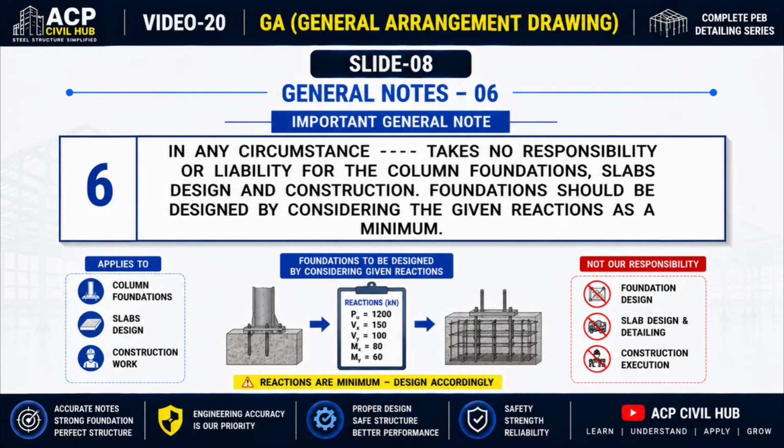The note also explains that the column reactions provided in the structural drawings are the minimum design values. These reactions, such as axial load, shear force, and bending moment, must be considered while designing the foundation. However, the foundation engineer should also evaluate site conditions, soil bearing capacity, applicable design codes, and any additional project requirements before finalizing the foundation design.